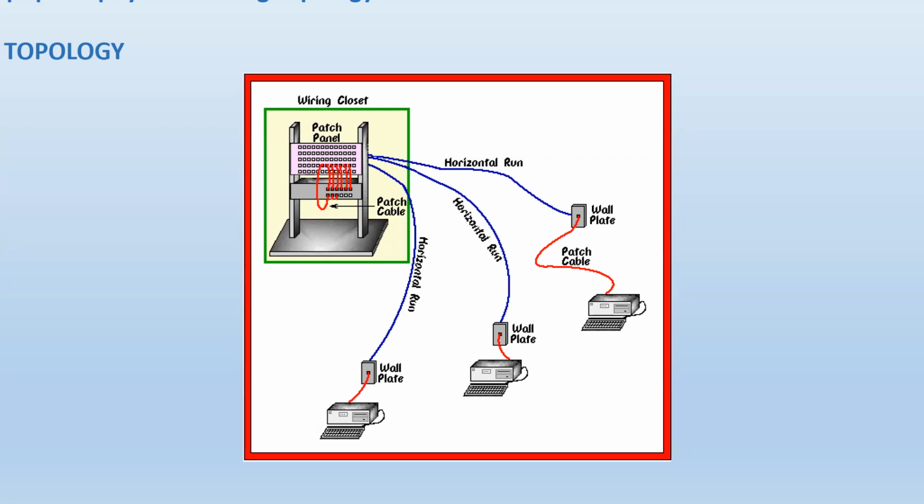So there's the main brain of the tester, and that tester, the certifier, goes through some rigorous tests and does some more rigorous frequency response and whatnot in order to certify a run as such. Like, for example, Cat5e, Cat6, Cat6a, Cat7, or so on. Right? And all those have certain specifications, and we're going to talk about those too in some further lectures. So that's the most popular activity that will be done: pulling wires, installing wires, terminating, testing, troubleshooting.